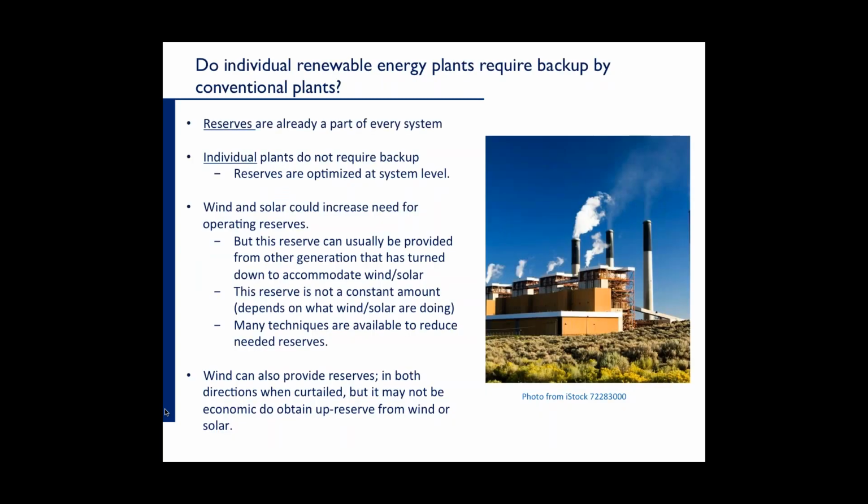People often ask, I have a 100 megawatt wind plant, don't I need to have a backup for that wind plant? And the answer is you could, but it would be needlessly expensive because we don't back up individual units in the power system. Reserve policies and methods that we have for calculating reserves take into account the entire system. We never back up individual plants unless there's some sort of a market imperfection that might otherwise require me to do that. But in every case, if you're building an individual backup, you're needlessly increasing cost.